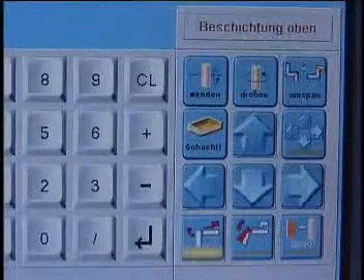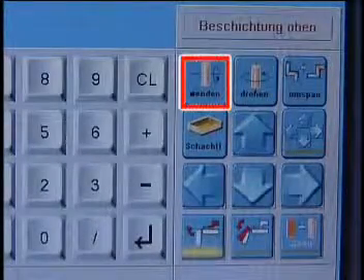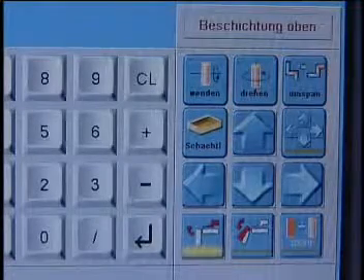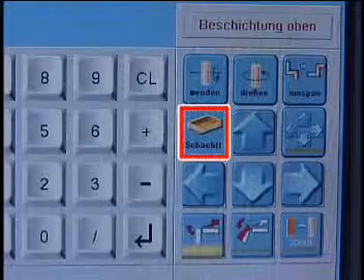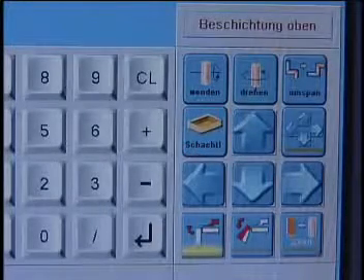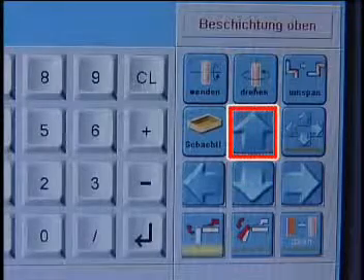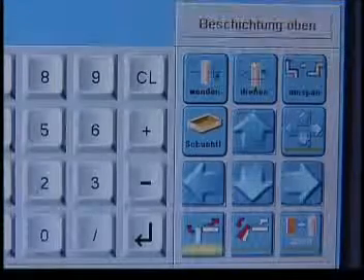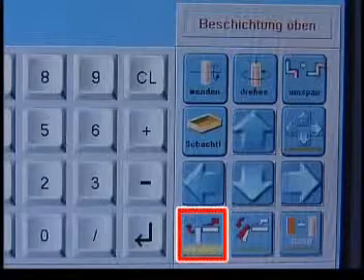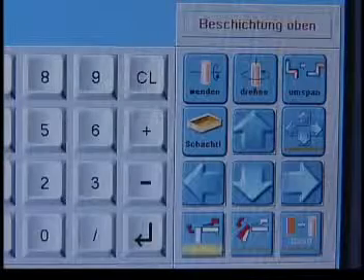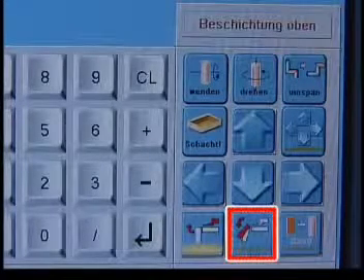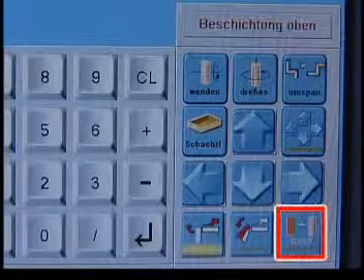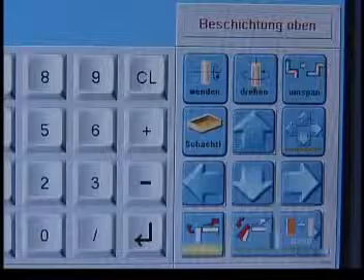In the first row, you will find the buttons for material handling, like turn, rotate, and reclamp element. In the second row, there is the submenu for boxes to bend parts on all 4 sides, the cursor up button, and the button to activate the scroll function. The fourth row starts with the power mode button to modify the speed of the folding beam, step bending to form radius, and a button to switch between 2 or 3-dimensional.